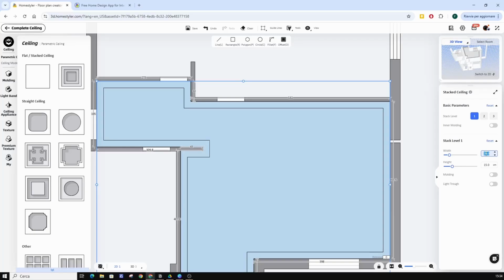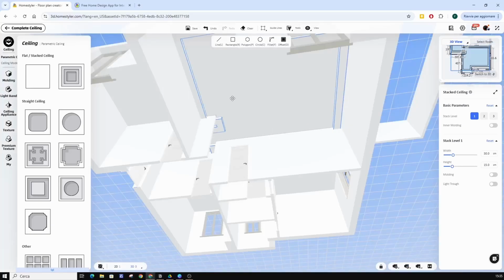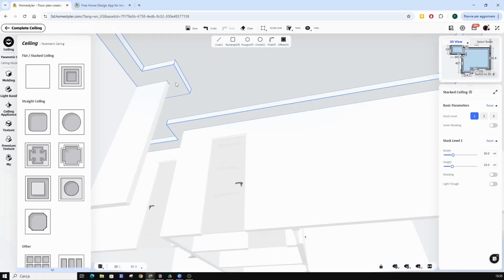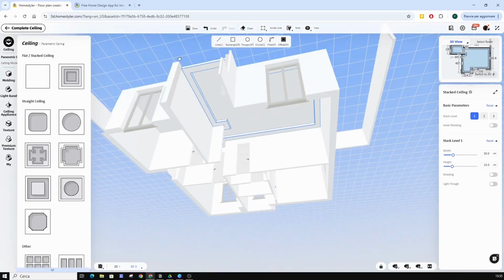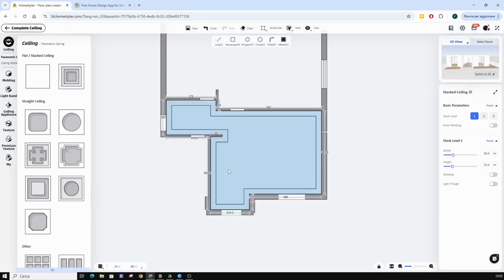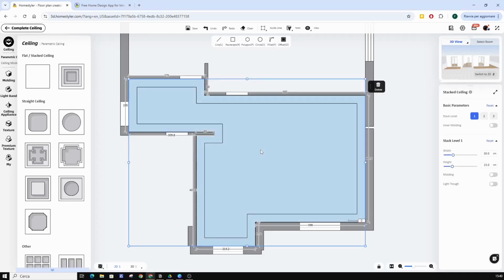We enter a value. Let's try to enlarge it and the height. Here it is set to 15. Let's go see in 3D what happened. Let's go back to 2D. If we want to undo the ceiling just inserted, we select it, and by means of the Cancel key, we can return to the starting situation.